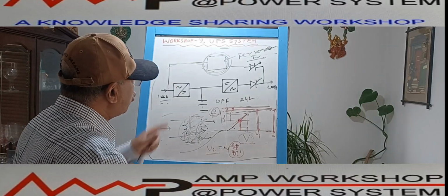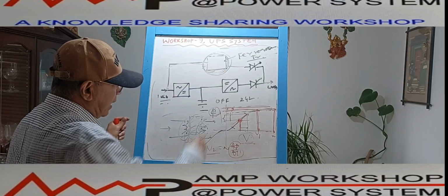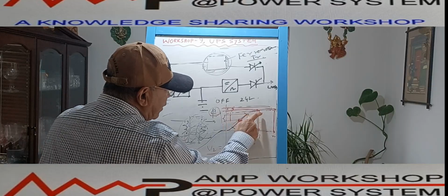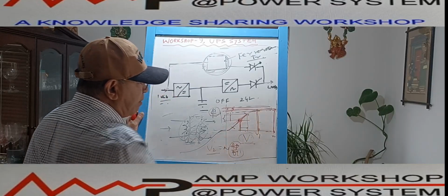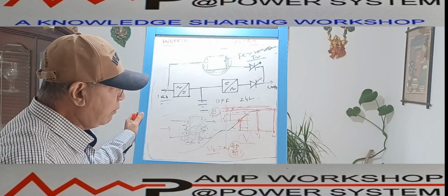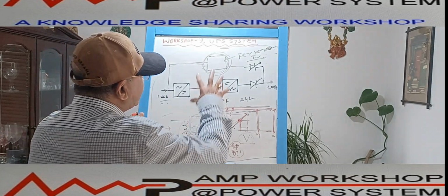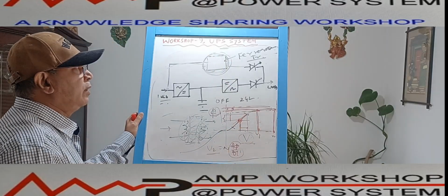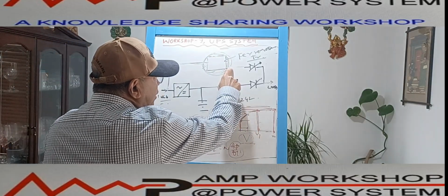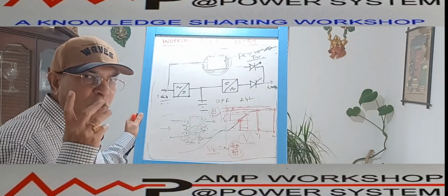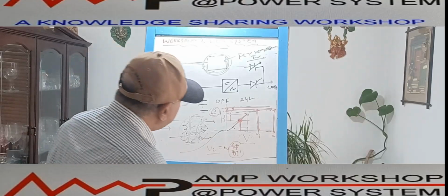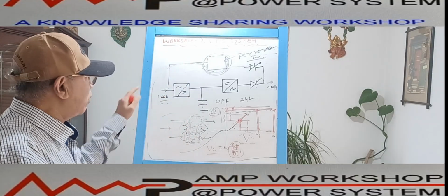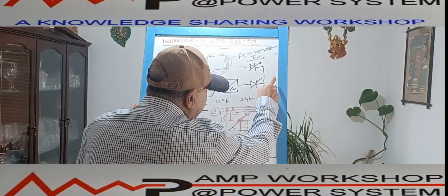If in this UPS system bypass line we use the magnetic core of the transformer and design the core at the saturation point of the magnetic curve, then what will happen? In that case, this transformer will work on the ferroresonance principle, and then the output voltage of the transformer will remain more or less constant. So what will happen in that case? The voltage fluctuation of the input will not be reflected to the load. That is one point.